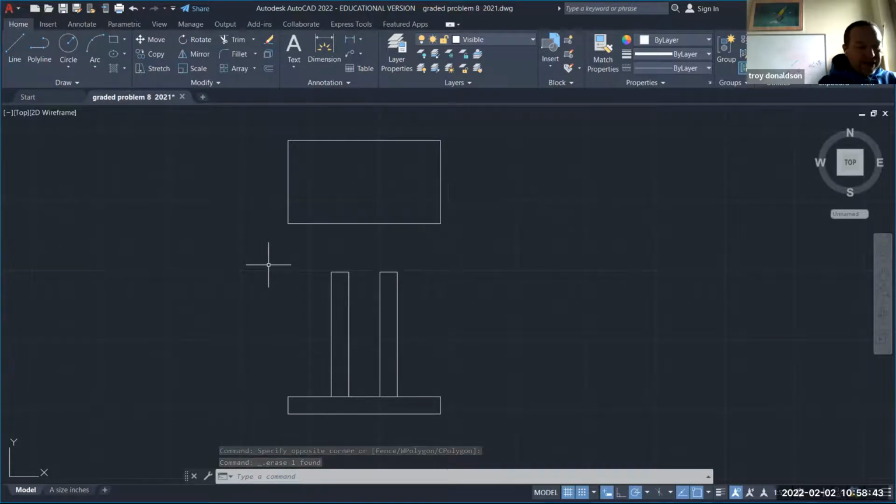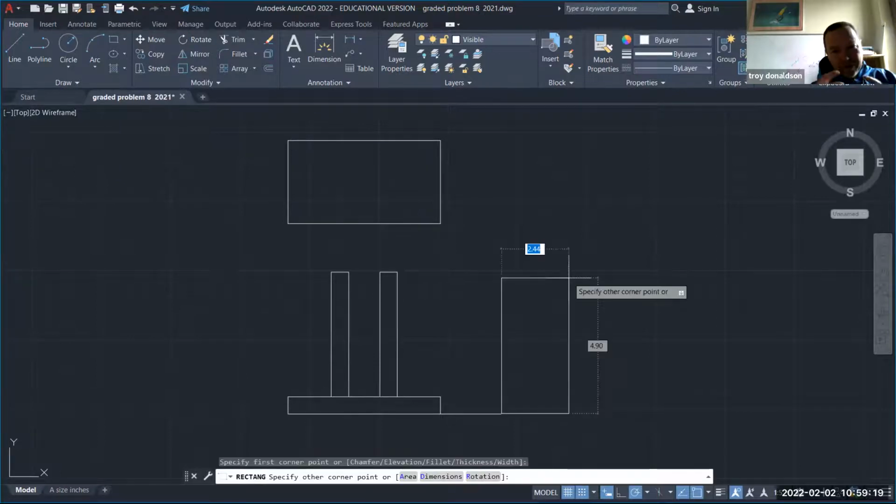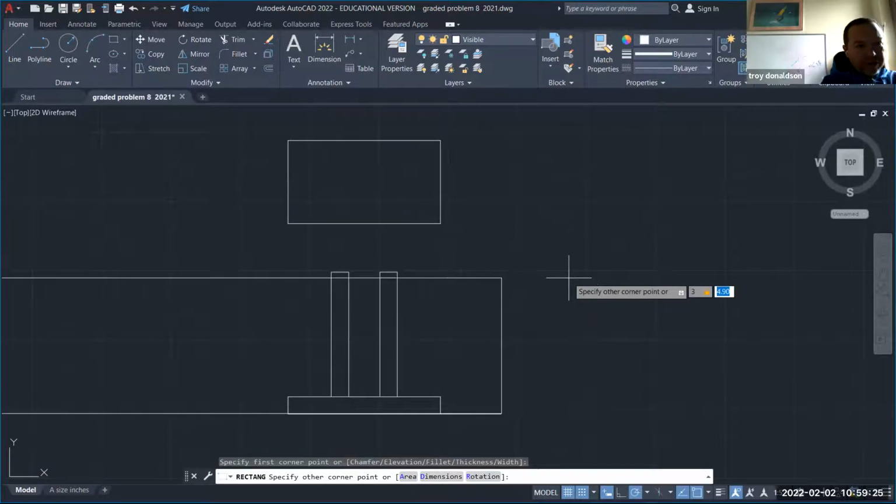Okay. Then I can do that again here, giving myself a little marker line. And then it looks like the right side view is going to be 3 across the bottom and 4.5 plus 0.62. So 5.12. I think that's right. 5.12. You'll do the math, I'm sure. All right, so then I can do my rectangle again. And these are just view boxes where the view is going to be contained in there. So this can be really helpful when you're trying to lay out.